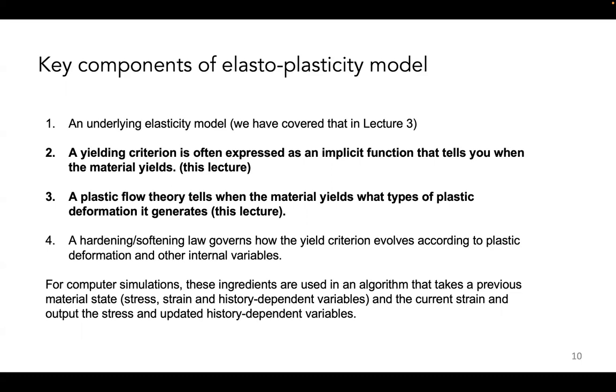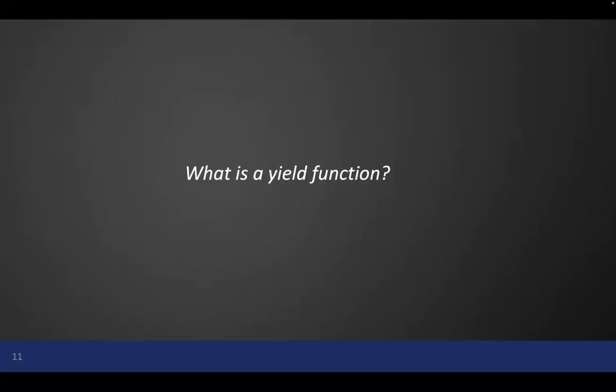Okay, so here we actually deal with a very specific problem. We just want to give in a strain history and predict the stress. I would like to define the problem in a very restricted manner. We are given the stress and the strain at the previous time step, the internal variable, as well as the current strain. Then what we need to predict is the new stress and the new internal variable, where the internal variable represents the history. In this lecture, we'll focus on the yielding criteria and the plastic flow, and how to use a neural network to generate those.